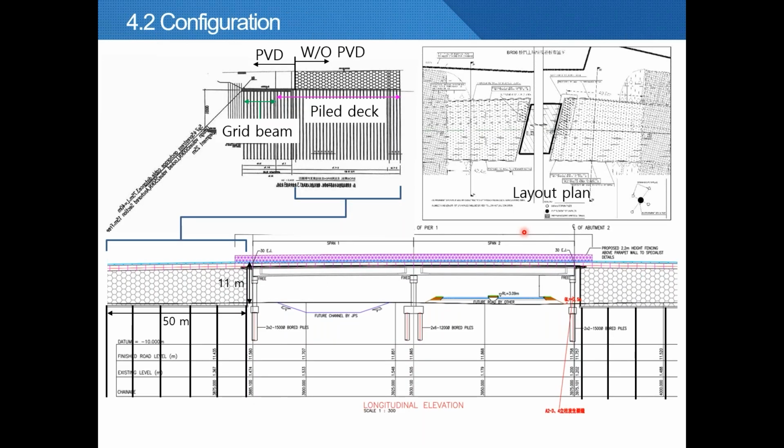This is the configuration. There are two abutments for the bridge. They are symmetrical. Both of them have shown some degree of distress. The bridge approach was made up of a reinforced soil wall supported by 300 mm diameter spun piles. The spun piles are 21 meters long, driven to set, and spaced at 1.7 meter centers. The reinforced soil wall is about 11 meters, tapering down to 9 meters, butting to the earth embankment here.